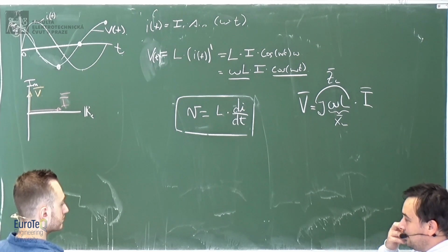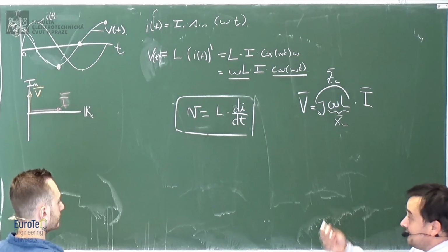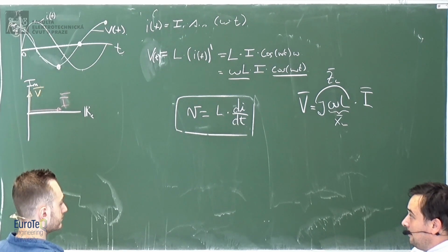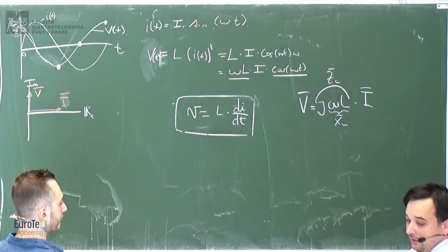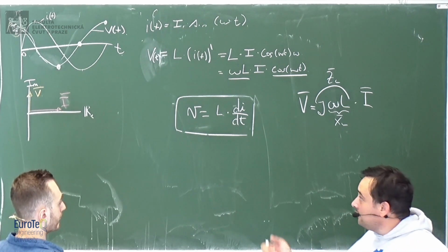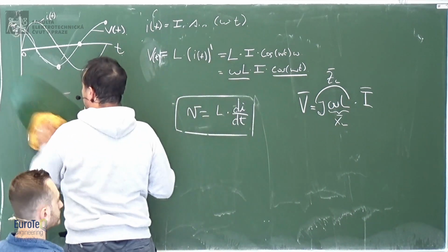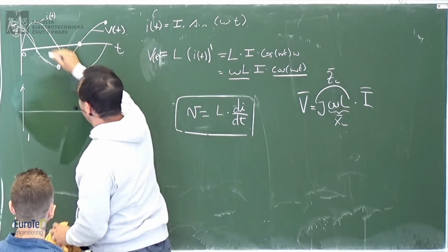With the capacitor, it was the charge which couldn't change instantaneously, and therefore also the voltage which couldn't change instantaneously. In this case, it's the magnetic flux. In fact, if you want, you can again make the same exercise where you take the voltage and the current. If you forgive me, I will cancel this, and you say, okay, here.